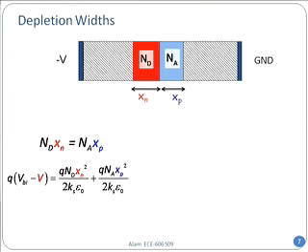When you put a bias, then it destroys this equilibrium. And as a result, diffusion now wins because the electric field has gone down. Right? Same distance, but QVBI minus V is the reduced barrier. So therefore, the diffusion current will dominate, and as a result, current will flow.